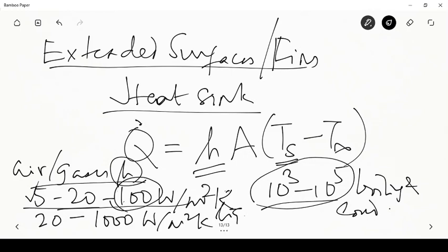Usually this temperature upper limit is of the order of about 50 or 60 degrees Celsius, about 15-20 degrees higher than ambient temperature, and the ambient temperature is going to be critical. So the difference between these two is going to be a critical one. In summer, for example, the ambient temperature can be as high as 30-40 degrees Celsius or 45 degrees Celsius, then the difference that you would have available would be very small, in which case this area A has to be substantially increased in order to provide for additional heat transfer.